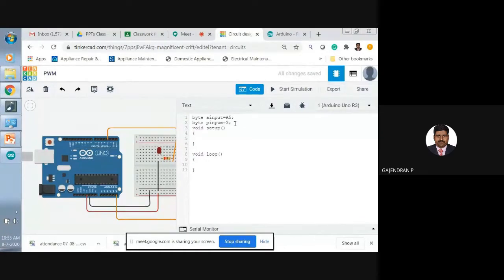So initially we declared the pin numbers. In void setup, we are going to configure the particular pin numbers for our current exercise. So pinMode. Hereafter, I am not going to type the pin number. I am going to use only this variable name. Okay. So analog input, comma, this one I am going to use as an input pin, isn't it? So INPUT, then PWM pin.